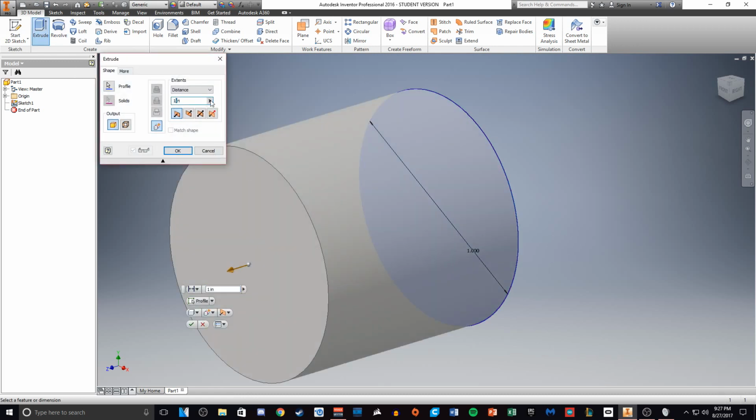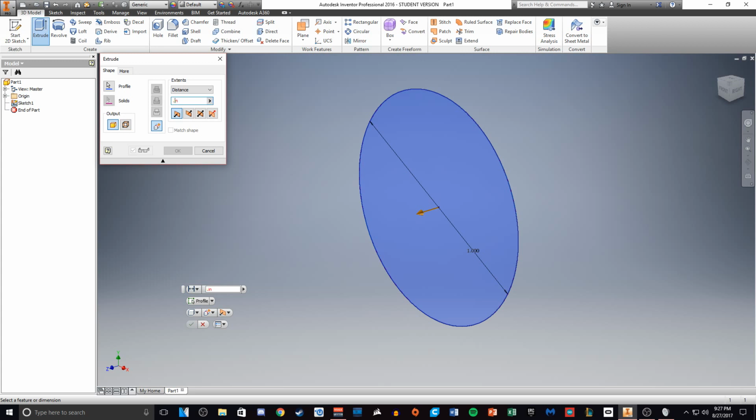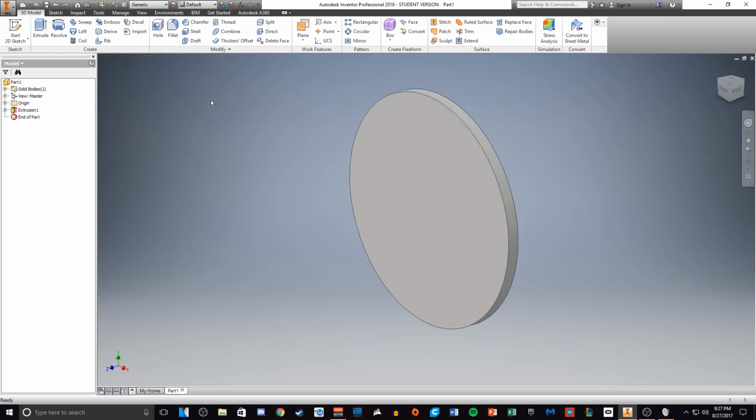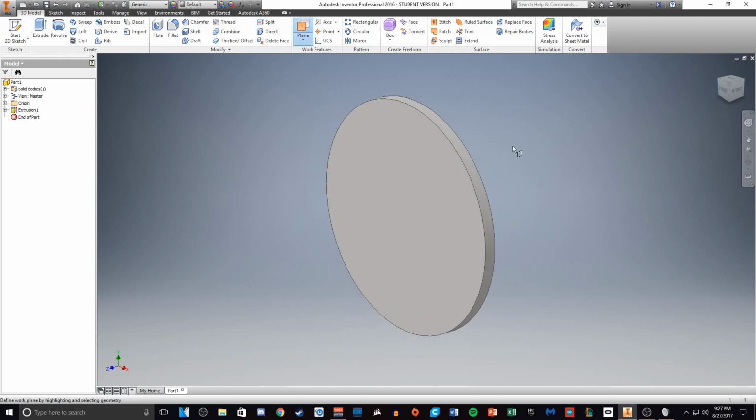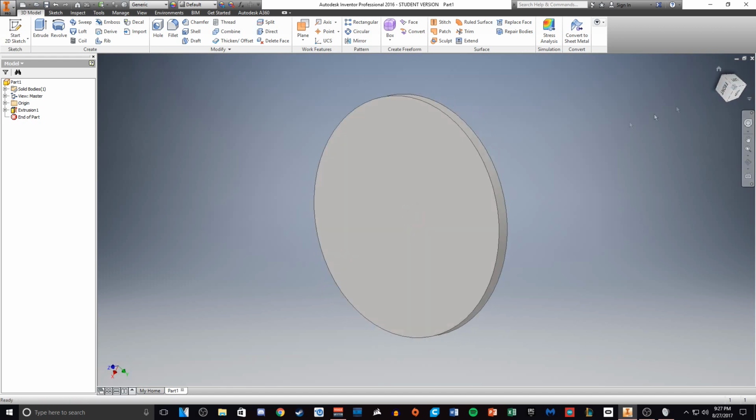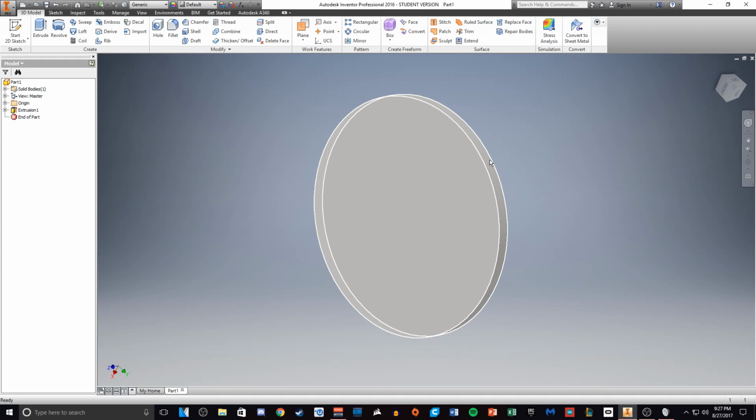We're gonna finish our sketch, and then we're gonna extrude. And let's see, we can probably extrude this 0.02. That's a bit thin. 0.05. That's probably better. 0.05 inches. Oh, oops. So this is what your wheel is gonna look like. That's the extrude function. It just extrudes anything from your drawing.